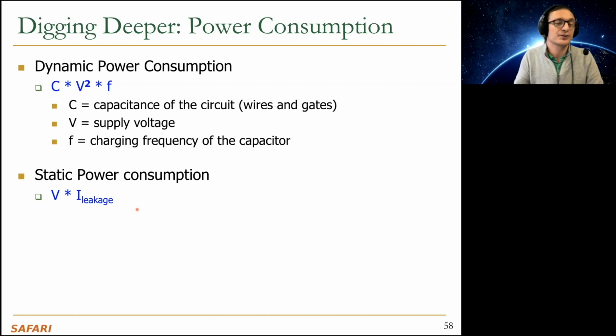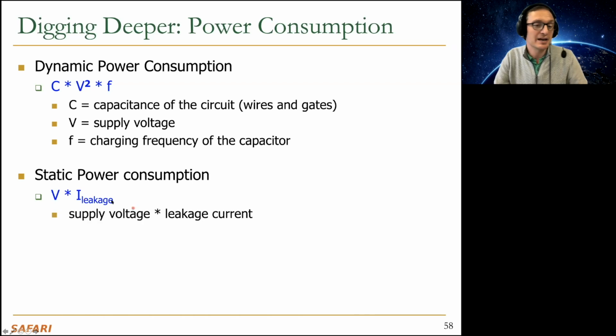It's a small amount of current, but it's leaking all the time. So it's not perfectly closed, meaning it's not perfectly open, let's say. It's somewhat closed a little bit, regardless of whatever is applied to the gate. Meaning that you're leaking, and leakage really leads to some power consumption. So there's a small amount of leakage current multiplied by the supply voltage that you have, and that's your static power consumption. And as you add more and more transistors, you basically multiply this value with the transistor count.